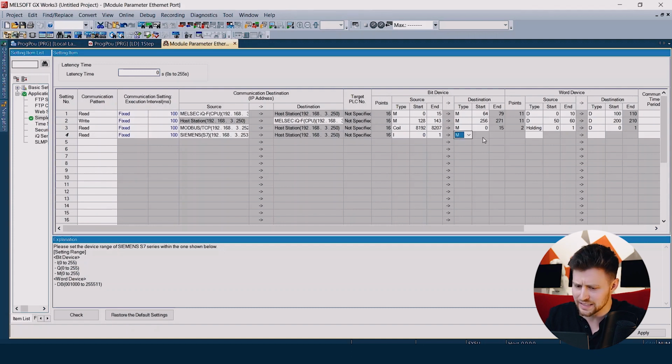And we can read this data and store it on the M registers from 16 to 31 in this case, because under every I address we can find 8-bit values. In the case of word values, they can be found in data blocks, let's say from 1000 to 1001. And we can store the whole word data type in one register, so let's choose, for example, 50.